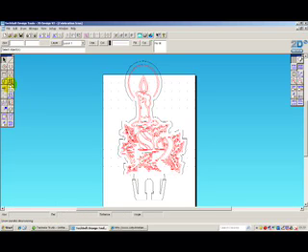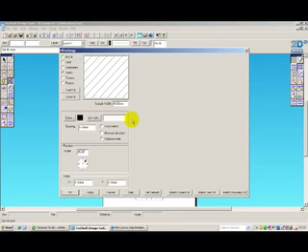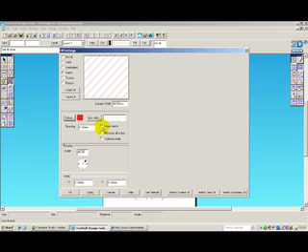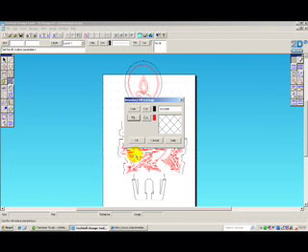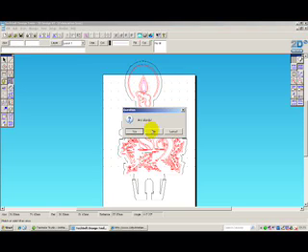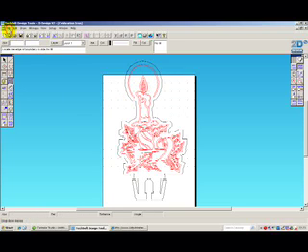The final thing I'm going to do is put a fill. I'm going to put a hatched fill. I'm going to make it red because I want it to engrave. And I'm going to cross hatch it and do it to a finer grid spacing, 0.5mm. Click OK. Click inside that centre, and I've given the flame a bit more boldness.